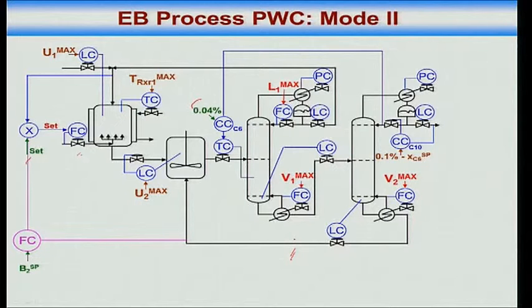Okay, so what I do is this. Now does this make sense? Does this make sense or no? Yeah. So now these are my two unconstrained degrees of freedom. This and this. These two set points the operator can play with. These are the same as I had told you earlier: product benzene impurity, and DEB recirculation rate. Okay. Alright, so I have synthesized the control structure.